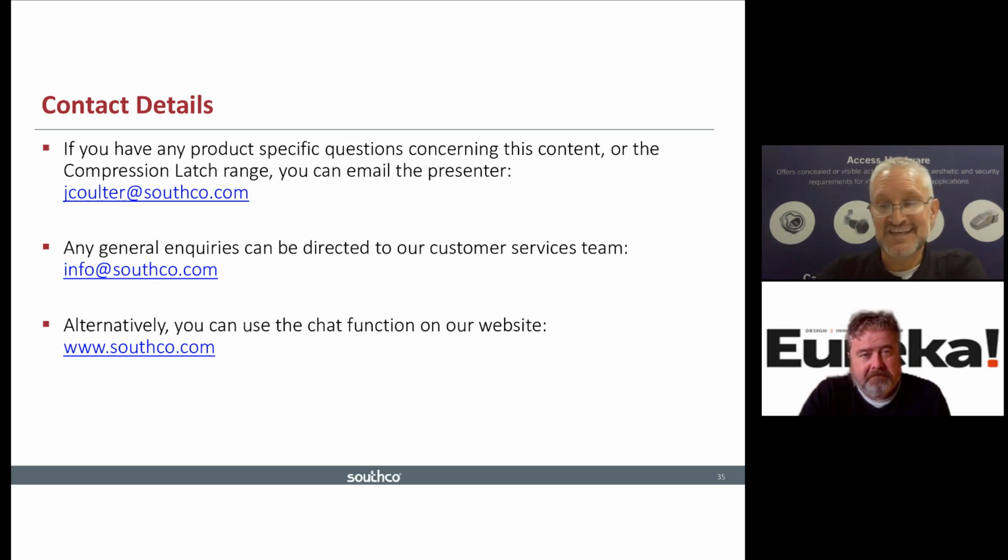If your application is on the inside of an enclosure or a building, let's say, and you don't have the harsh environment, maybe it's okay to use a lighter material, whether it be a plastic or aluminum or zinc. So those are also ways to determine a material. Another application requirement is the load it'll see.